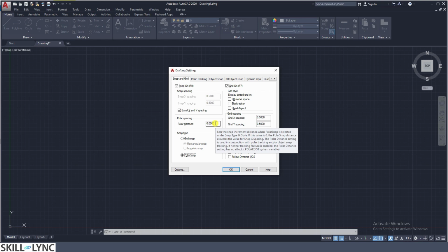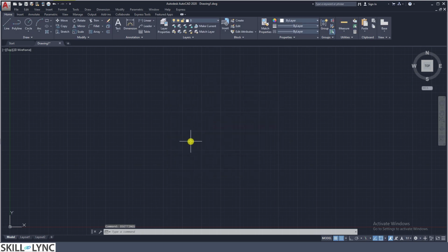So based on that, for example, if the snap value is 0, it is for a uniform snap spacing in x. If we specify an alternate unit, say it is 0.25, so your snapping is enabled in that manner.